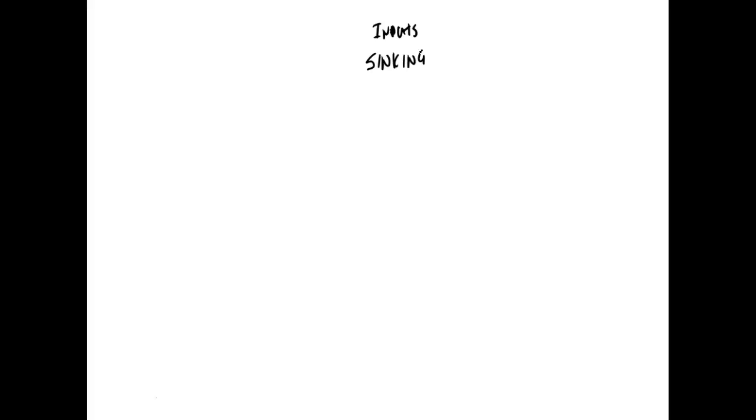You buy sinking inputs or you buy sourcing outputs if we're dealing with DC. Sinking and sourcing only come into play if you're dealing with DC, not AC. Everybody understand that? So normally we hook up our inputs sinking, and we hook up the outputs sourcing. So what does that mean, guys? I've got my input.